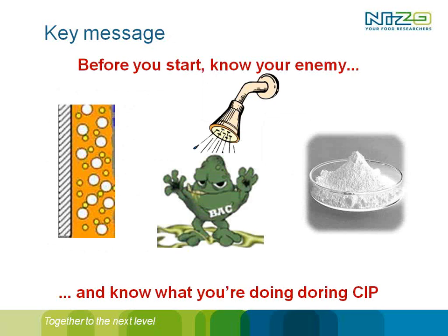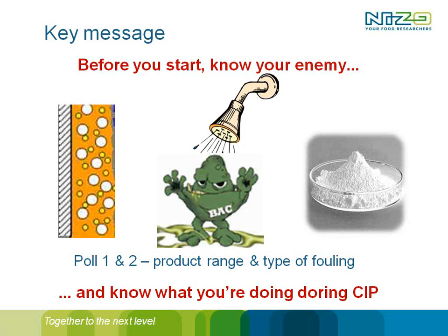What you see on this screen, for example, are various ways of fouling. For example, bacterial fouling, mineral fouling, or protein fouling. And it's very important that you're aware of this type of fouling before you start doing your CIP.